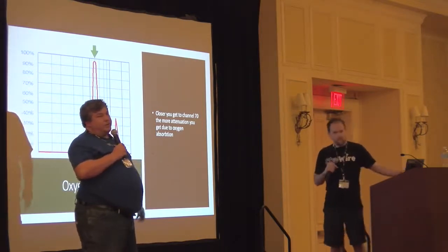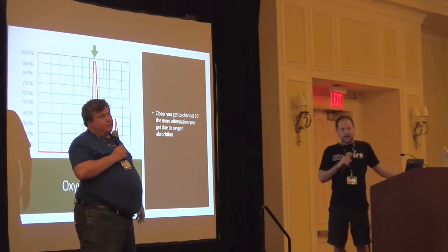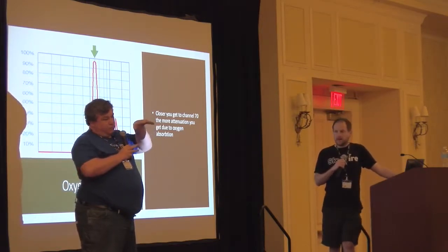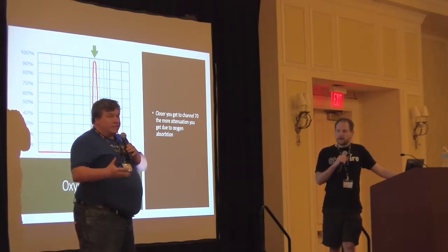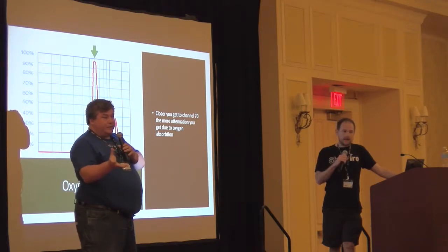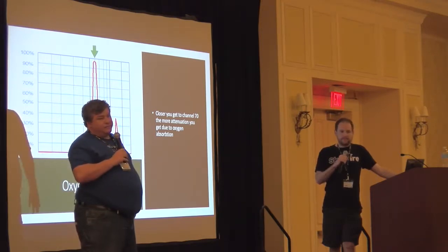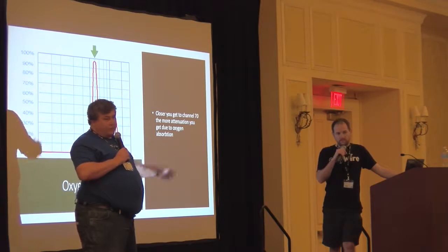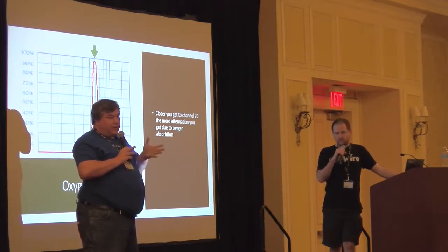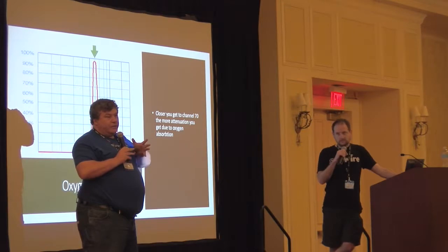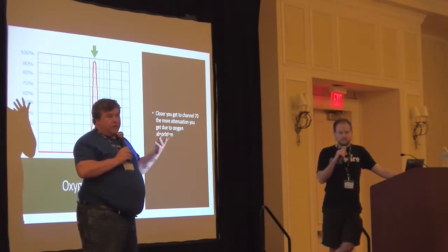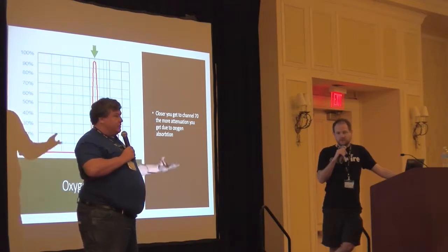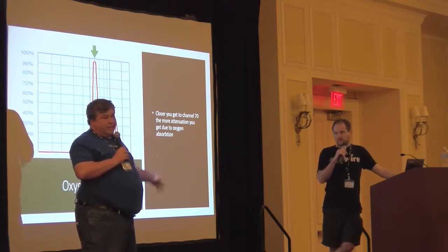We always kind of follow the 3 foot rule, but there's been poles where they're almost touching each other, and the only reason we're not touching is we don't want the bleed over from the card inside the unit to affect the other one. Yeah, a foot would be sufficient. Really, you don't have to worry about the beam at that point. You just have to worry about the RF from the card bleeding over into the other one. And there's enough channels where you can kind of get away from that too.